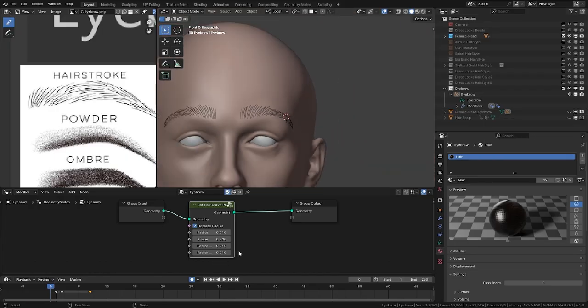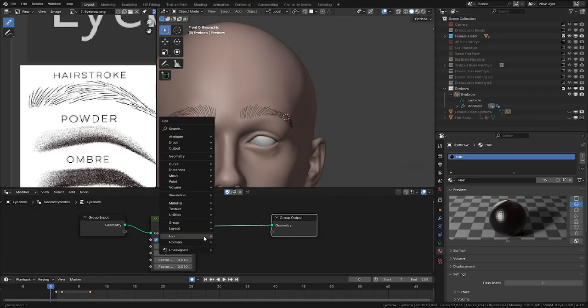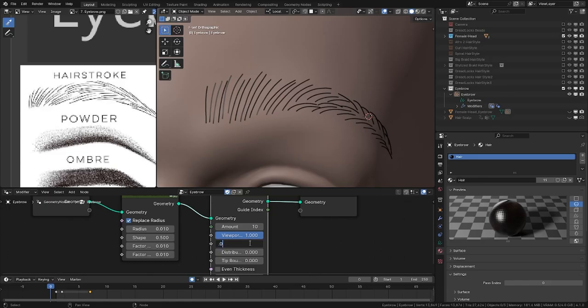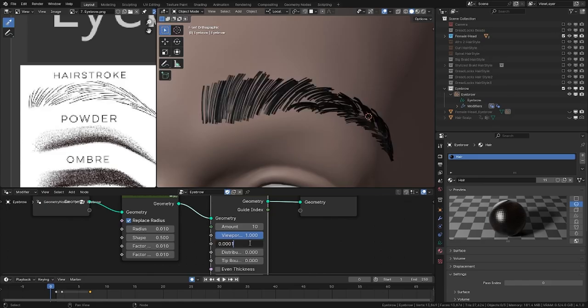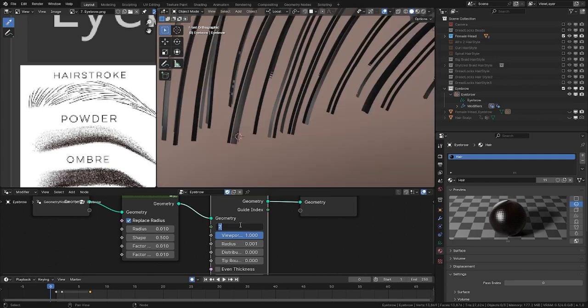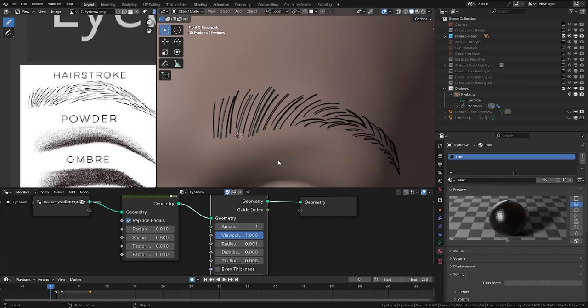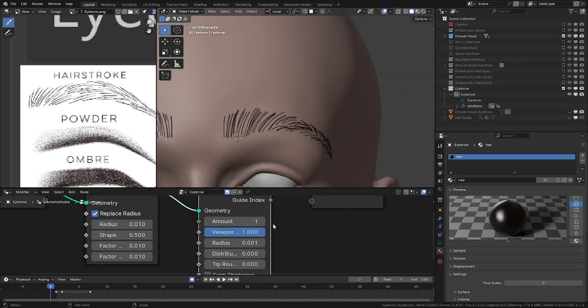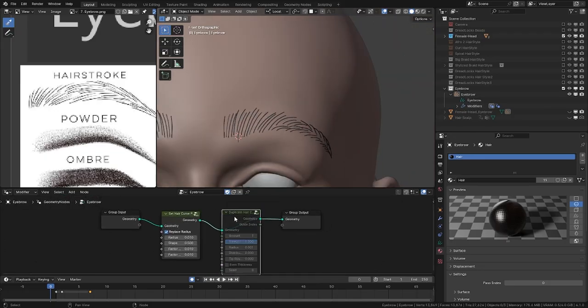You can either use a duplicate. Let's say, what if we use a duplicate? Come to generation and then duplicate, then you will do the radius 0.00115. And here I'll put the duplicate to 2. What about 1? That's 1 is enough. And then I'll increase it to 1. So we can even use a duplicate, or we can disable it. And next, let's disable, remove it.